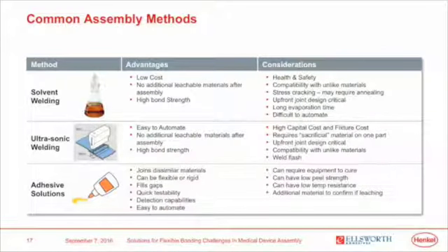On the challenges side, there are going to be some cases that we'll talk about today where they do require equipment to cure. The good news on that is that many of the new equipment sources in the marketplace today are lower cost LED solutions, so we'll talk about those. The adhesives can have low peel strengths, as well as some grades can also have low temperature resistance, so just something to keep in mind if and when selecting an adhesive solution.